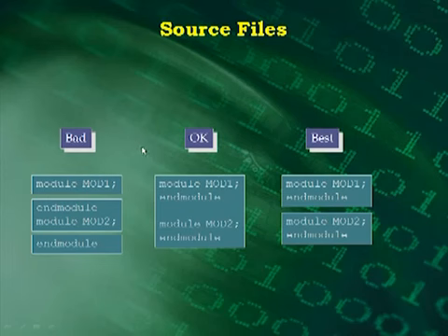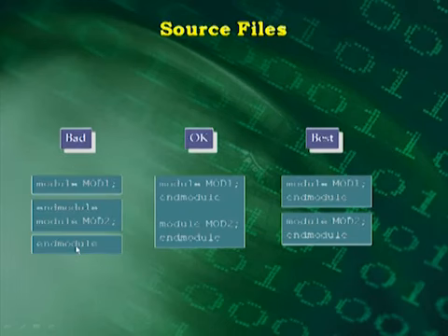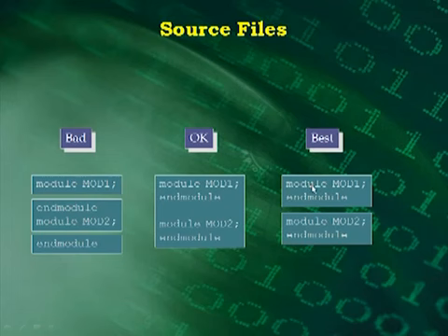Here's an example of what I'd say is bad, okay, and best. Here somebody put module mod1 in a file, and they put the endmodule for it at the beginning of the next module in a different file, and then endmodule in a third file. I'd say that's bad. I'd spank somebody if they did that. And here's a couple examples where somebody's put two modules in the same file. That's okay, but in practice, I think it's best if you separate each module into its own file.